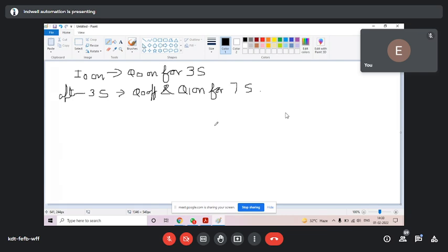Saurav, you have broken latch from M1. It is not correct. Let me see. M1 is not there. Okay, let me check once more. I0, M0, M0, Q0, M0, M2 has come. See, M2 will break the Q0 ladder in your program. M2 will break the Q0 ladder, the second ladder.